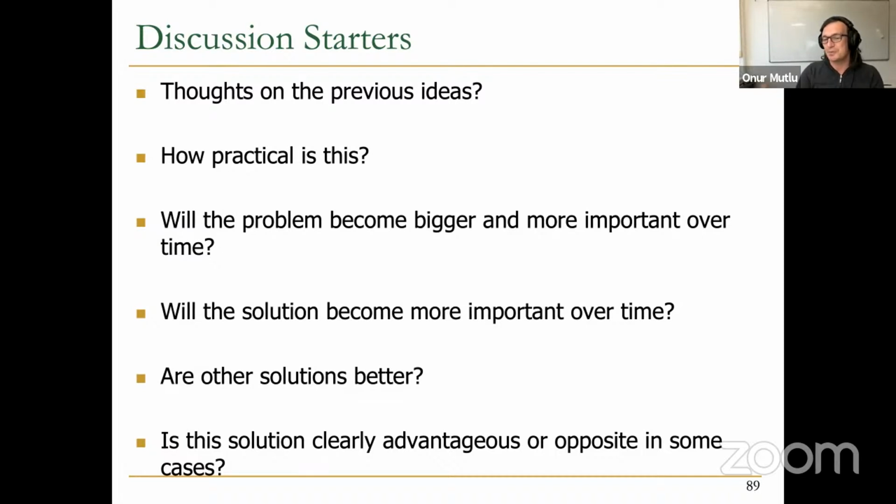I think there are multiple. So I think in the general purpose computing sense, you're right. It requires operating systems to be more, let's say, intelligent from my perspective, more aware of the hardware topology of DRAM. There's another way. I will first answer it from a special purpose perspective where you don't have an operating system, like a machine learning accelerator, for example. You have your dedicated DRAM or a GPU where you have a lot more visibility into your DRAM. I think these sorts of ideas are a lot easier to adopt in those systems where you don't have to go through an operating system to process data.